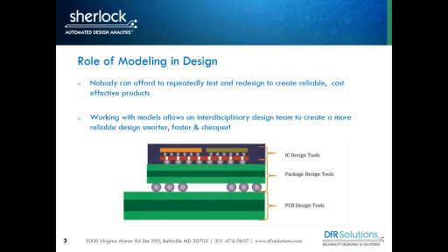If something fails a qualification test, you've already gone through a fairly large, lengthy development phase. You've gone through prototyping, maybe even HALT testing, and then something fails. You have to go back and redesign and repeat that whole process. So we're really looking at it as an interdisciplinary design team. There could be people doing reliability on the IC, the packaging. Usually, though, that's not what the end user is going to be dealing with. You've got the electronic packages, and how does it affect the PCB reliability. So it just makes everything go faster, and it actually makes it a lot cheaper to develop a robust product.